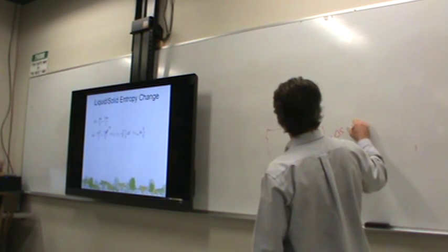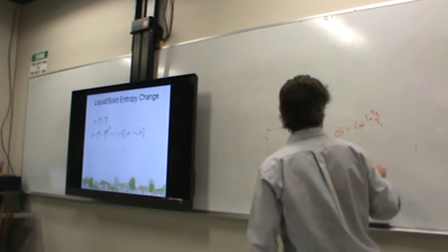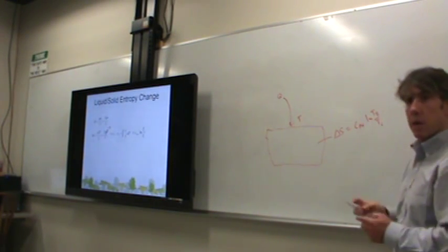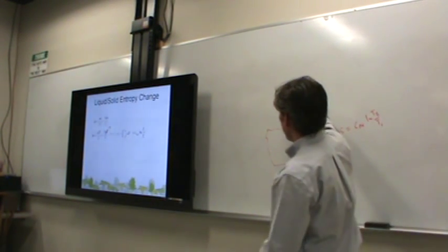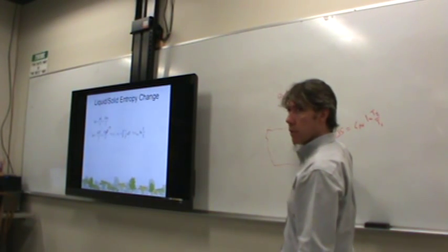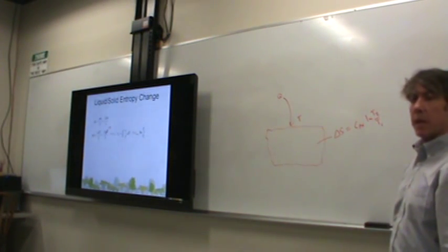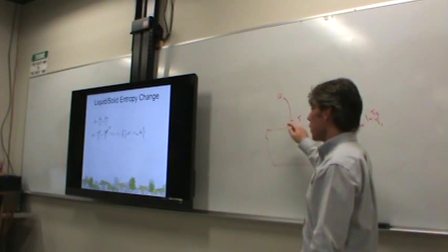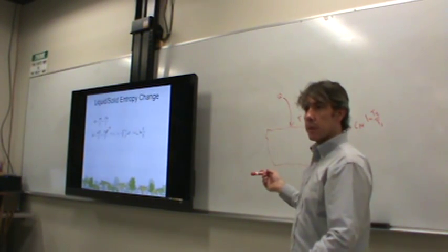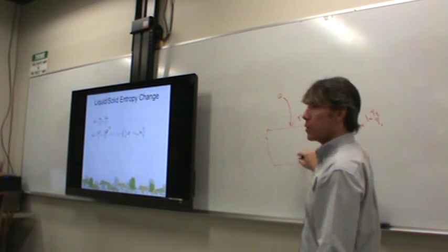you can calculate it as the average heat capacity times the natural logarithm of the temperature ratio of the water, where T2 is the final temperature of the water, T1 is the initial temperature. Now, if you calculate both of these, you find that the amount of entropy transferred into the water via the heat transfer is less than the change in entropy of the water. Why would that be? Why would there be more entropy in the water than what was transferred in? Because heat transfer is irreversible. Make sense? And since heat transfer is irreversible, some entropy will have been generated.